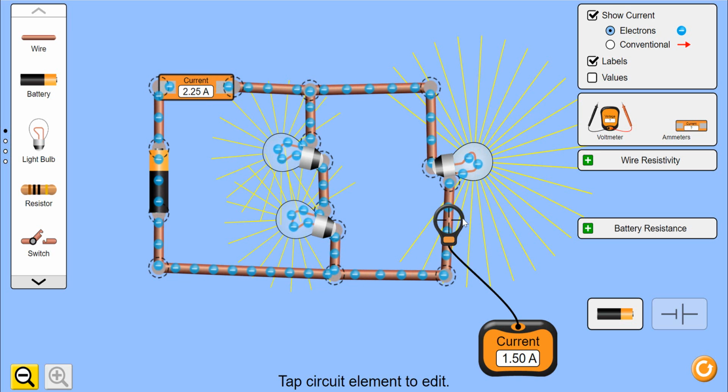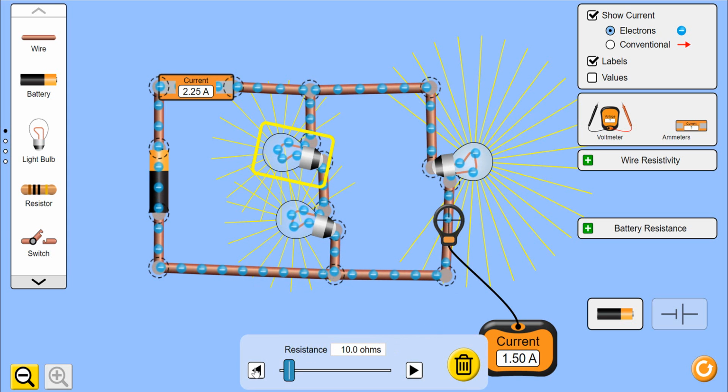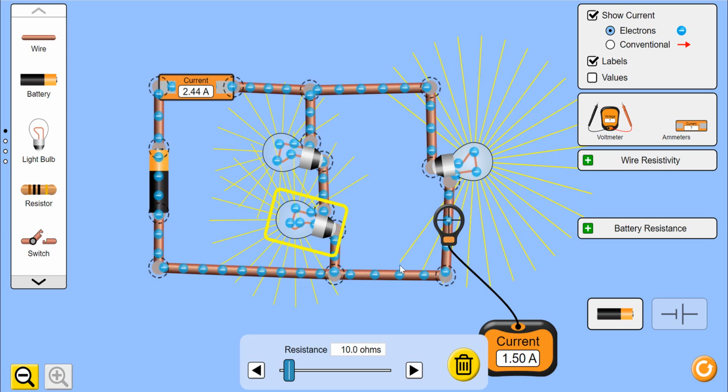Just before I deal with that light bulb burnout analogy here, let's make these resistances what we had on the notes. So this first one here was a 6 ohm resistor. If you can track the brightness as I'm changing this here, that's 6 and this is 10 ohms. Let me track this down to 4 ohms. As I decrease this one here, you're going to see slight changes already with what happens to the brightness.